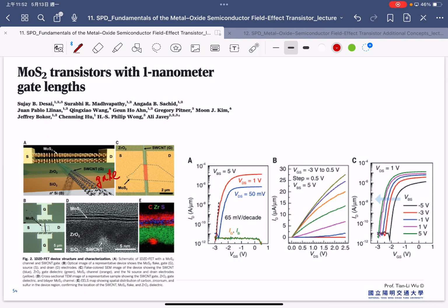Why do I say switch off? Because if you look closely, the threshold voltage is negative. So that means this is actually a depletion mode transistor. That's why in the beginning we were talking about depletion mode. Most students will forget that in the MOSFET we still have a depletion mode, but right now you see that the depletion mode is still sometimes useful for us.